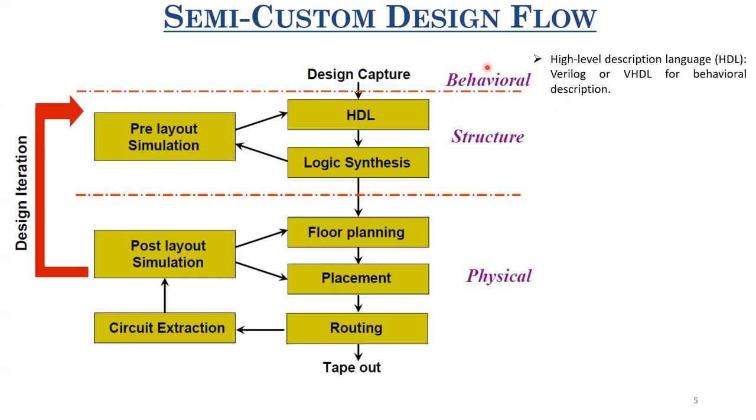You just write the behavioral code for the input-output relation, or the truth table of that case. You are not interested in how exactly it will be implemented on hardware, or what exactly the circuits are that would be implementing it. At the behavioral level, you treat it as a black box. You only relate the inputs to the outputs. So what you write in HDL is a behavioral model of the system.